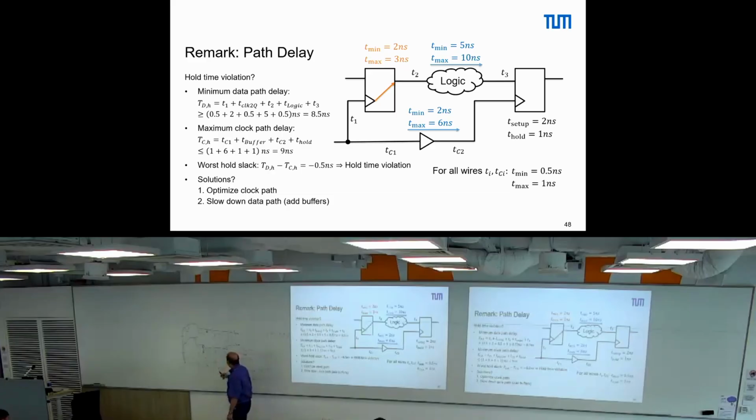But we can run at a higher frequency that is determined only by the OR gate. Right? Now we are maybe back at the problem that here no buffer is inside. So we may have to add a buffer. But that depends really on the wiring and so on. So this is how we would approach it if you really have these setup and hold time problems.